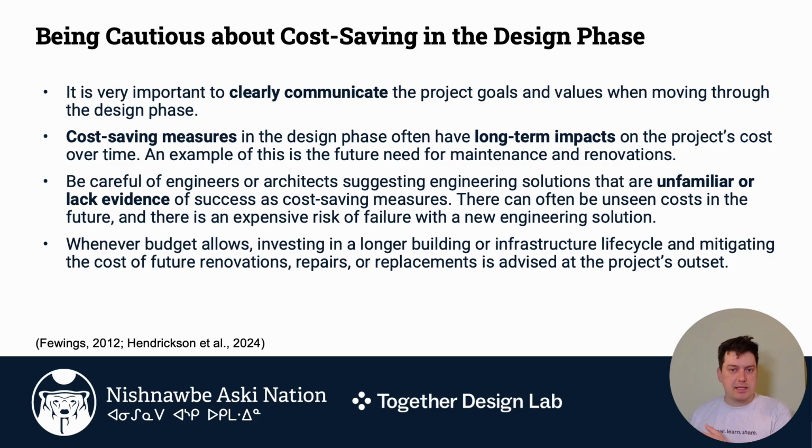So it can be things like energy costs going up in the long term because you reduced some insulation, or you went with a lower grade window, or other things that can make the operation of the building more expensive in the long term. Or it can be things where you opted for a lower quality product at this phase that means that it breaks down earlier. It has a shorter life cycle and adds to the maintenance costs of the building.